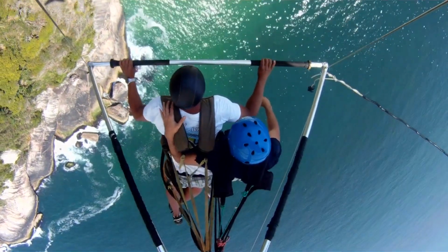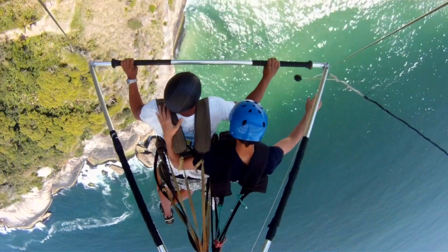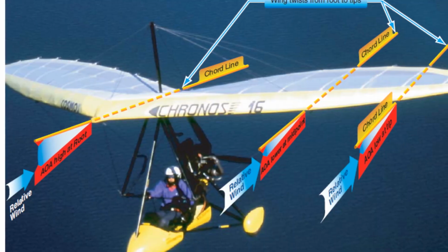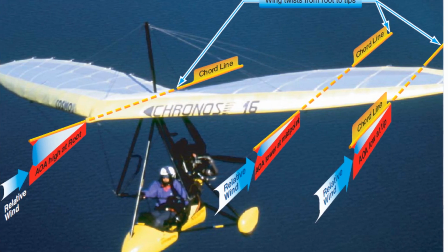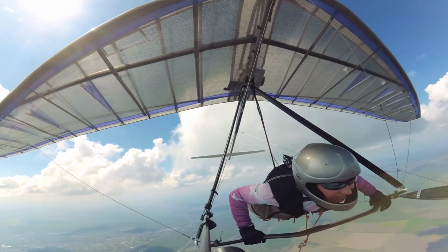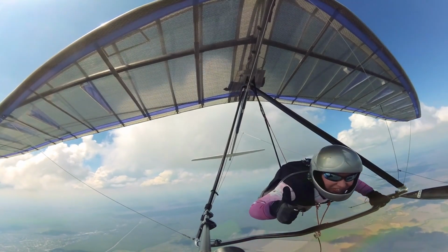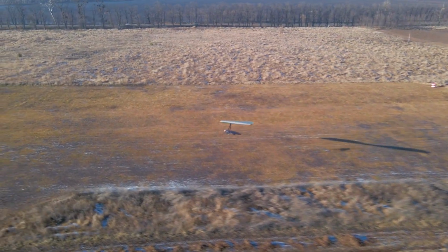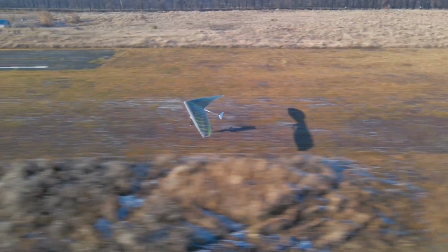Now, let's dive into wing twist, the decrease in chord angle from the root to the tip chord, ranging from 5 degrees to 15 degrees. This twist, also known as washout, is crucial for the aerodynamic characteristics of WSC wings. The longitudinal axis is an imaginary line about which the aircraft rolls around its center of gravity, also called the roll axis. The angle of incidence is the angle formed by the root chord line of the wing and the longitudinal axis of the WSC aircraft.